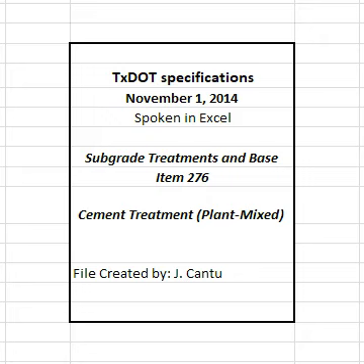2.1 Cement. Furnish hydraulic cement that meets the requirements of DMS 4600, hydraulic cement, and the department's Hydraulic Cement Quality Monitoring Program, HCQMP. Sources not on the HCQMP will require testing and approval before use.